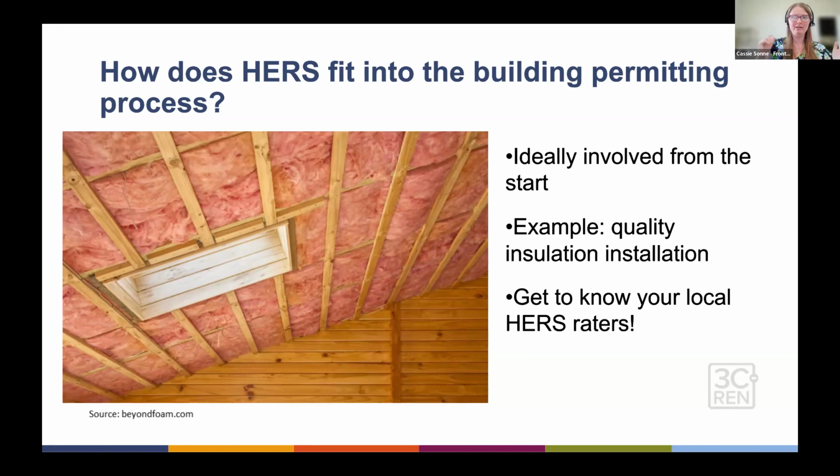Well, as we just talked about, contractors must correct anything that fails a HERS test, but the HERS rater only sees covered insulation. That leaves 2 options. The first is the contractor removes all the drywall, which is very expensive, or they attempt to create an energy model for the building that complies without quality insulation installation, which is often impossible and definitely very expensive. So having that good communication from the start between the rater, installer, and contractor, and having the rater inspect the project thoroughly during construction is really highly recommended. And this will also typically result in fewer change orders.